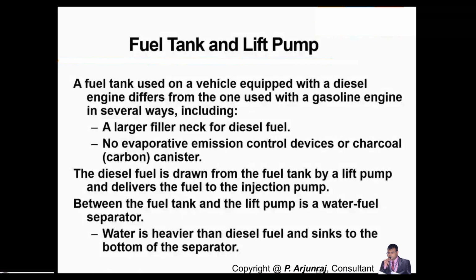And the diesel fuel is drawn from the fuel tank by the lift pump, and it delivers the fuel to the injection pump. And between the fuel tank and the pump, there is the water fuel separator, because it will separate water and the fuel. Water is heavier than the diesel, and it sinks to the bottom of the separator. Basically, this system is used to eliminate the water content. It will separate the water from the fuel.